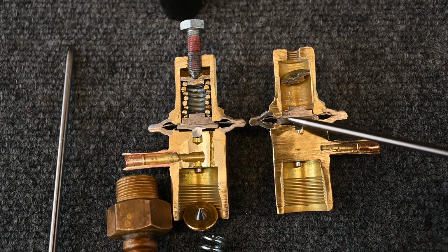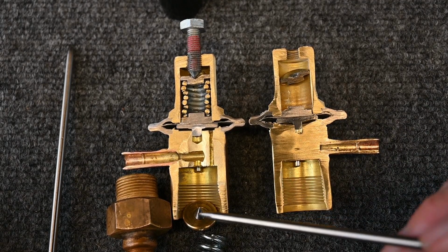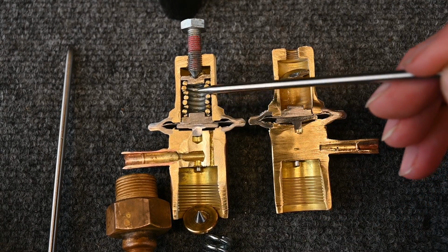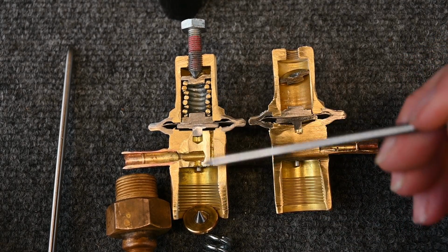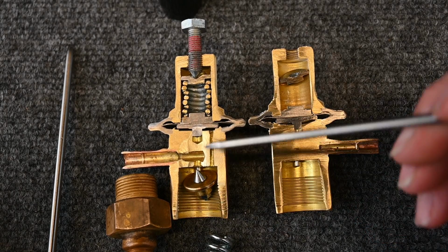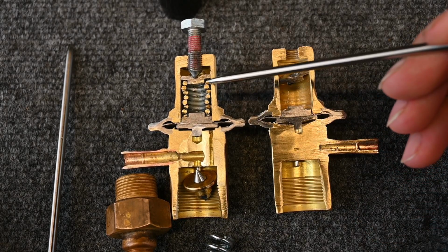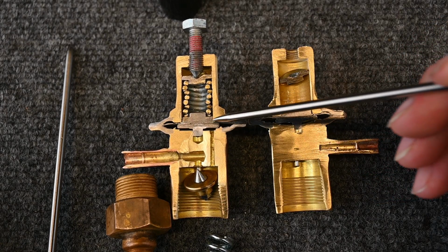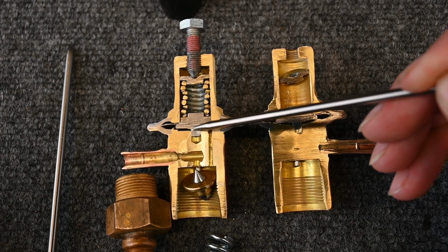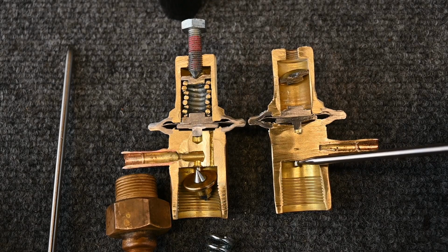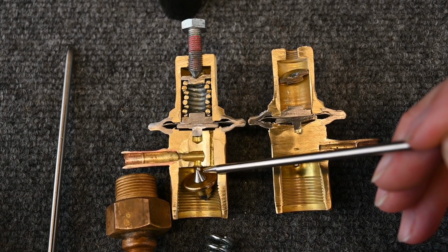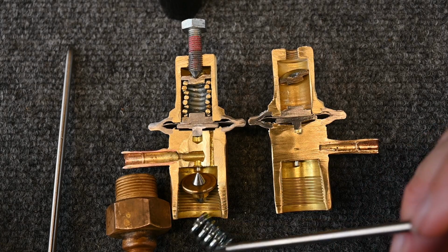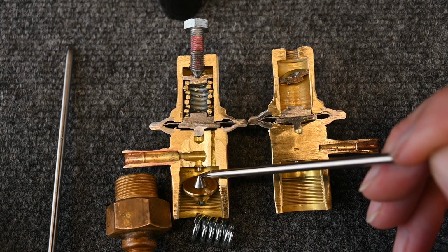So it's pretty cool how this keeps it all separate. These two pins are pushing down equally on this ring here on each side. So the pressure here on this spring pushes down on the pins to force this valve open. So as we increase the pressure here, more pressure on the spring, more pressure against this plate, more pressure against the diaphragm, more pressure against this plate, which means more pressure on our pins, and our pins put more pressure on this disc, which pushes pressure against our spring and causes this valve to open.